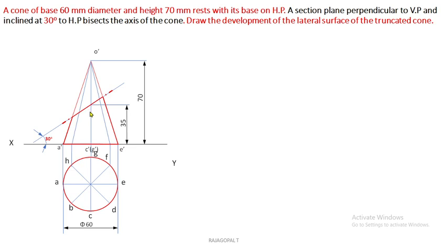Identify the section plane cutting points. Before that, convert the remaining portion into continuous thick lines. Above the section plane is the removed portion, and below the section plane is the remaining portion. Being a cone, only the boundary surface will be there, so convert the boundary surface alone into thick lines. No need to convert these division lines. The boundary surface of the cone has to be converted into thick line in the remaining portion.